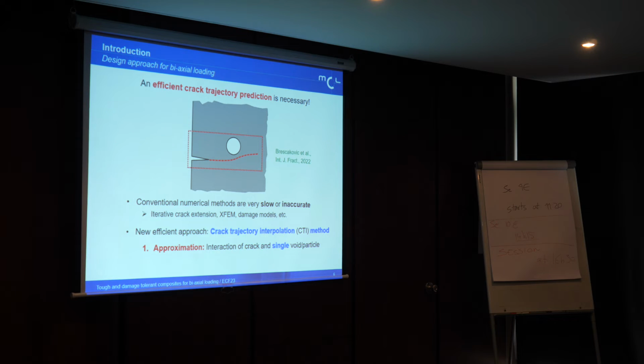First, the crack propagation can be determined by the investigation of a crack and just one single void. And second, the crack propagation through a multi-void array is then, because of our linear elastic material, accomplished through a linear superposition.